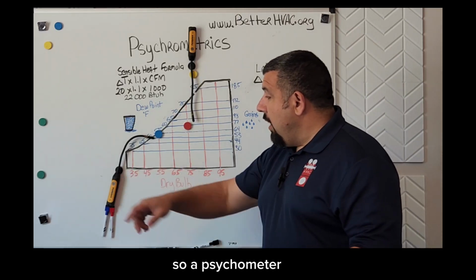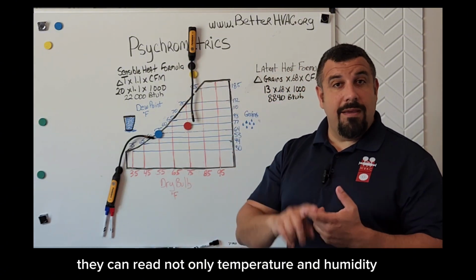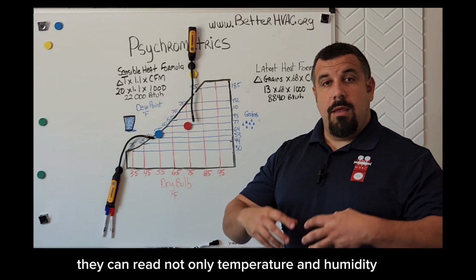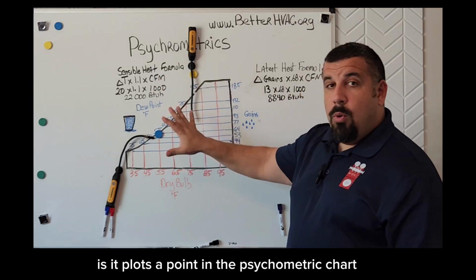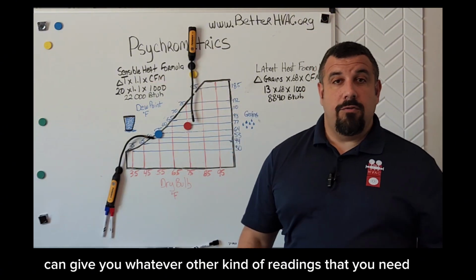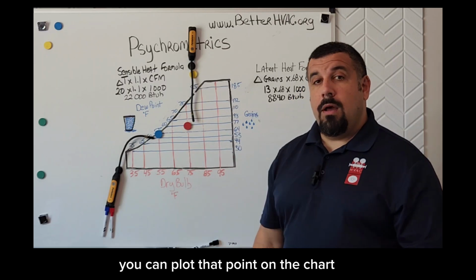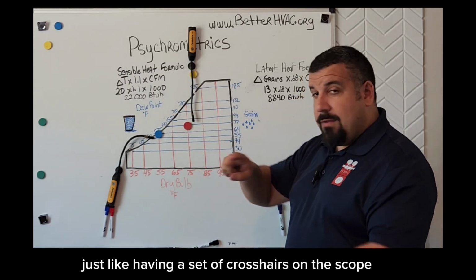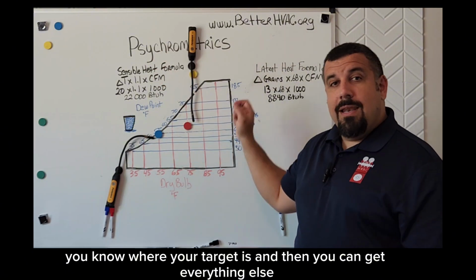So a psychrometer, like the ones that you see here that I've got from Fieldpiece, can read not only temperature and humidity. And once you can read both of those, what it does inside the app is it plots a point on the psychrometric chart, and then it can give you whatever other kind of readings you need, because as long as you know two things, you can plot that point on the chart, just like having a set of crosshairs on a scope. You know where your target is, and then you can get everything else.